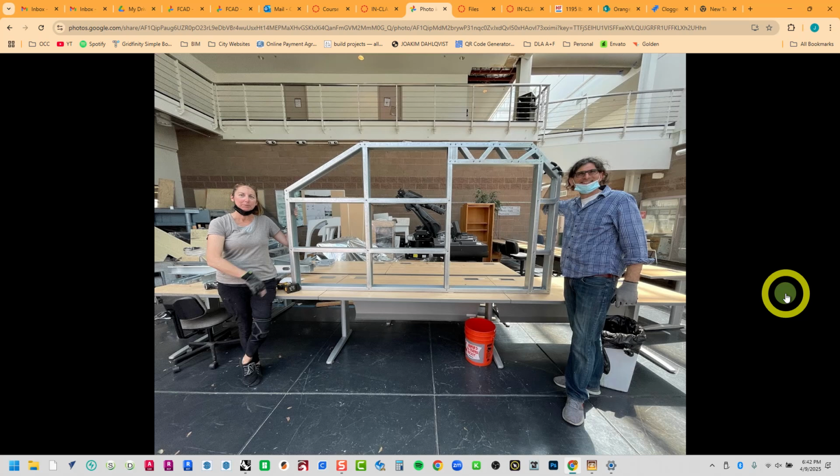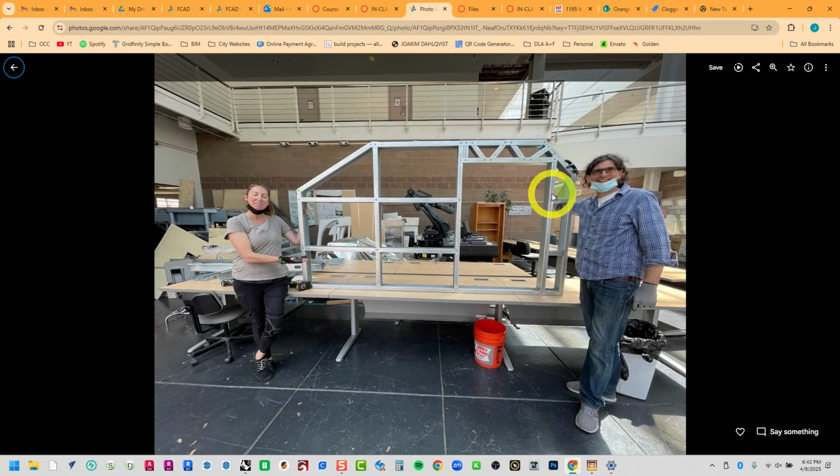This is a little door opening right there. You see that header, that webbed header that's in there? That was just a detail added in FrameCAD Detailer. We just said, hey, this is an opening, and it said, all right, we'll frame it as such.